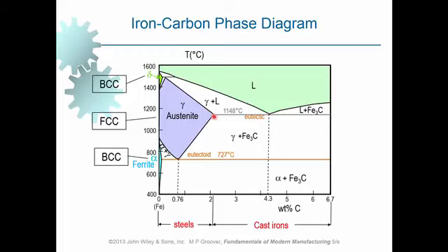As we can add more and more carbon to the steel, we make it harder and harder. So if you want to make it hard, it's better to elevate its temperature to this region so that you can add more and more carbon to it without formation of a second phase or intermediate phase. It is all solid and there is only a single crystal structure, and that is FCC or gamma. So there is a lot of carbon in it, and still a second phase is not formed. Then cool it down rapidly.